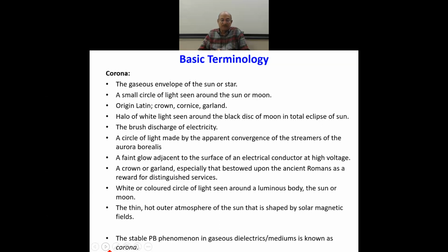And when we apply a voltage to this electrode, the field in the air achieved is very, very high, and the air starts losing its insulating properties at the tip of the electrode. Electric field exists only in the dielectrics because an electrode is an equipotential surface. Electric field unit is volts per meter, or take it kV per millimeter or kV per centimeter.